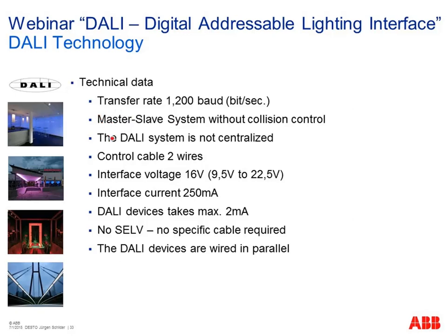And the next point, the DALI system is not a centralized system. We need only a DALI power supply, DALI control elements and DALI operating elements, so there is no PC or central device running which polls all our DALI devices. For the communication between all our 64 DALI devices we need only 2 cores of a cable, or 2 wires. On the next slide you will see more about the topology and how we can connect all the devices to the DALI system.